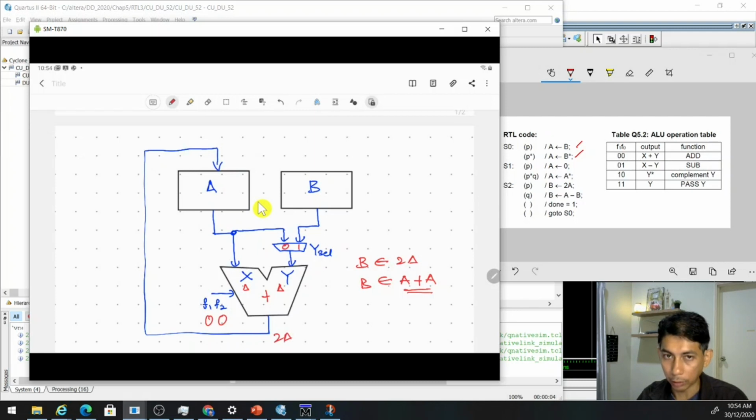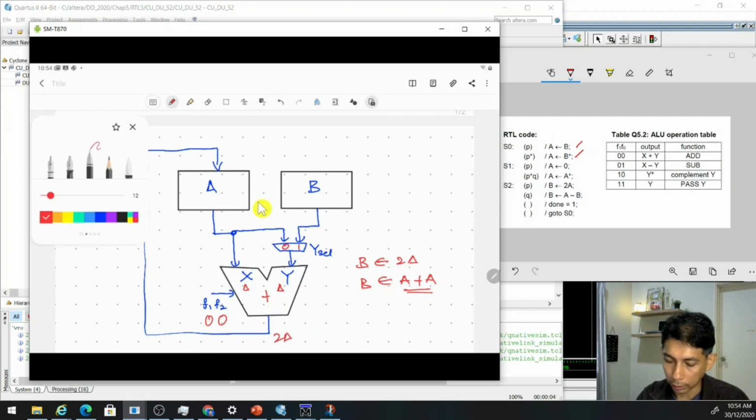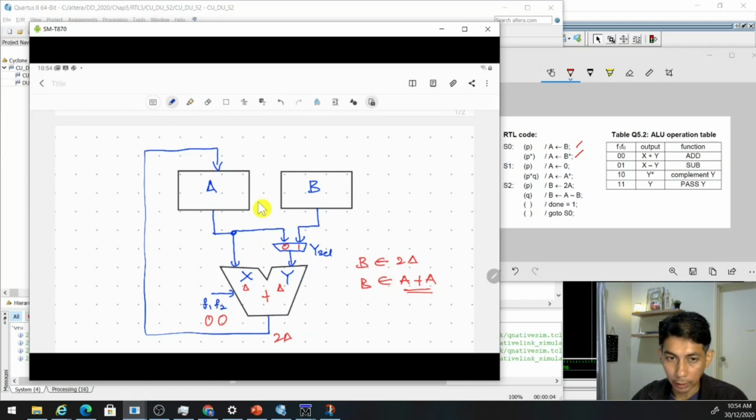So you have A here and you can have 2A here. And send to B. Now you want to send to B, so you need another connection, which is from the ALU into B. So you can share the bus, should be no problem, right? And this line to A is sent to B, all right? Here for this, should be no problem. And next one is A minus B and store at B. So whether we need a new connection or just use this connection can be done or not. Yeah, the last operation. So we want to do A minus B again.